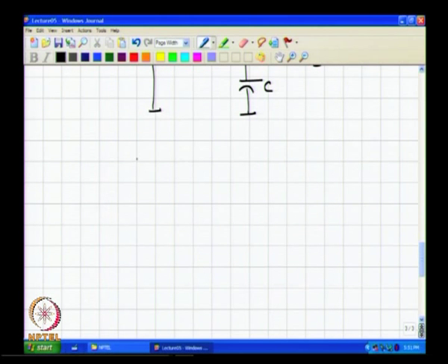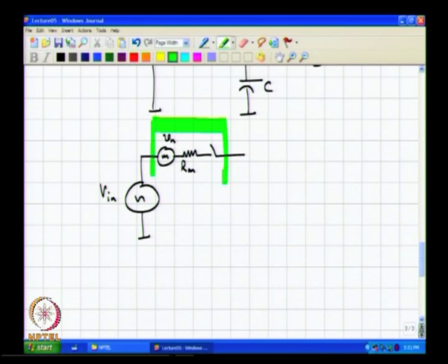What this means is a couple of things. So, now if there was an input voltage in addition to the noise of the switch, let us model the switch as a noise source, its on resistance and an ideal switch. Okay. So, this is a real switch and I have here the sampling capacitor.